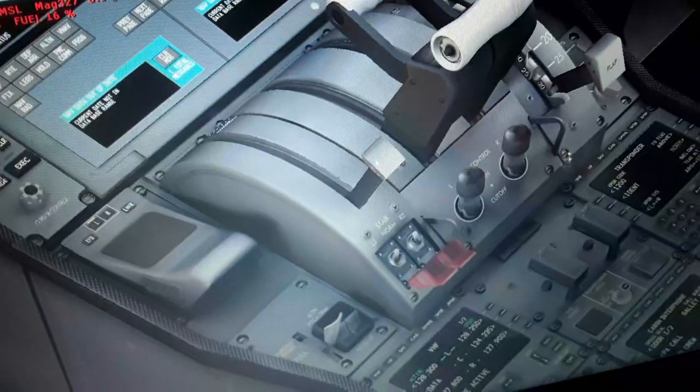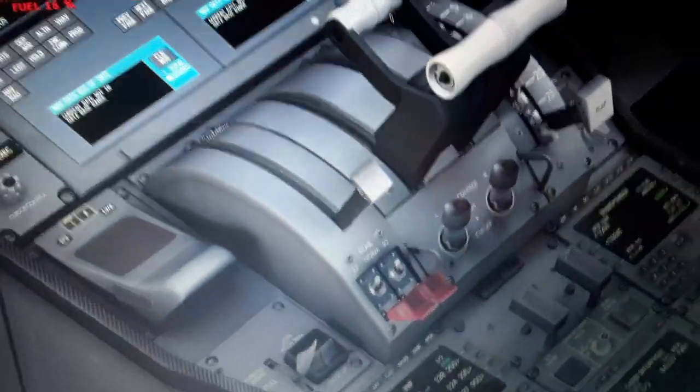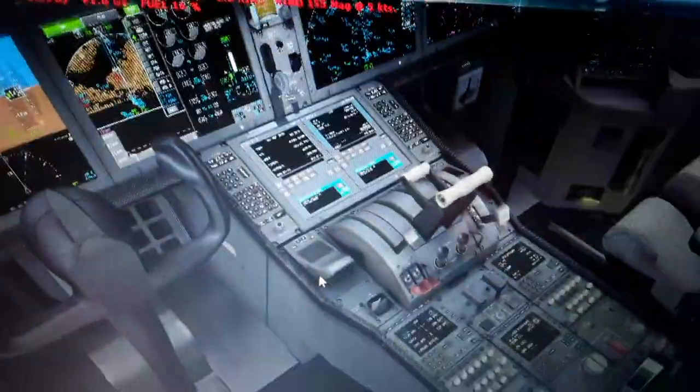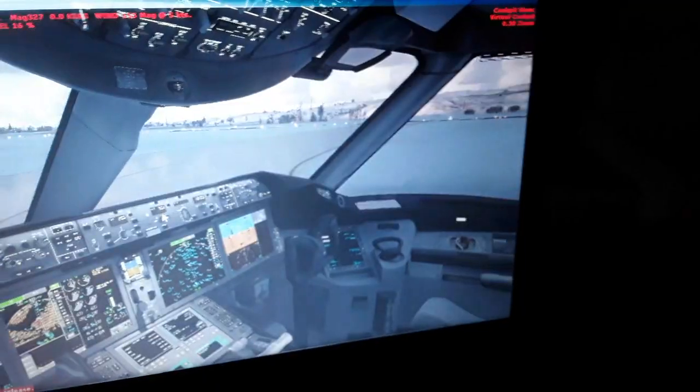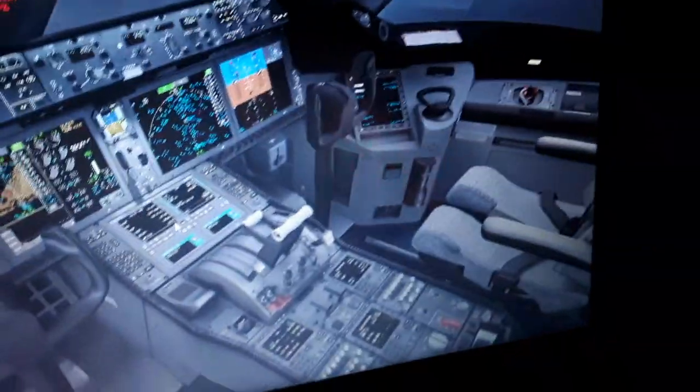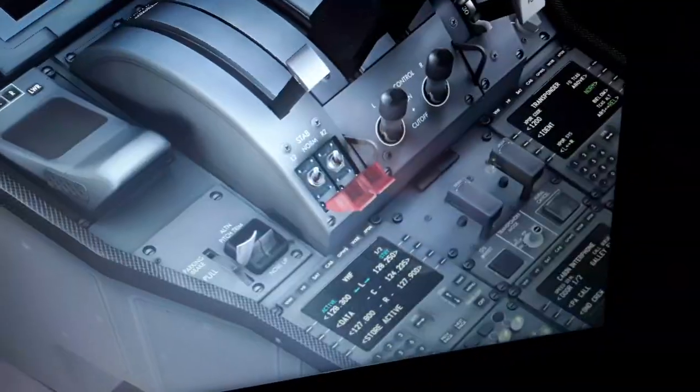Also we have the flap speed here. So this is the control wheel, its functions, the rudder pedals also. So it's very easy. You have also, as I told you, the horizontal trim stabilizer. When you fly, the elevator will be moving up or down by trimming it. You don't need to use so much the yoke for the elevator. So it relieves the pressure from that and balances the aircraft in flight.